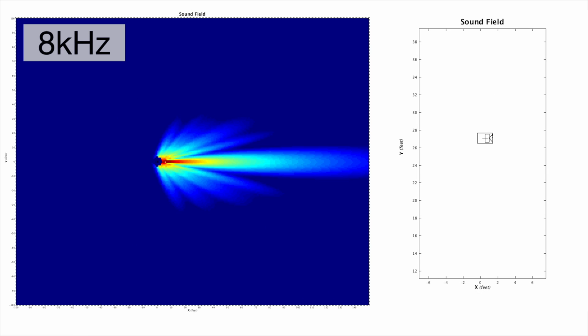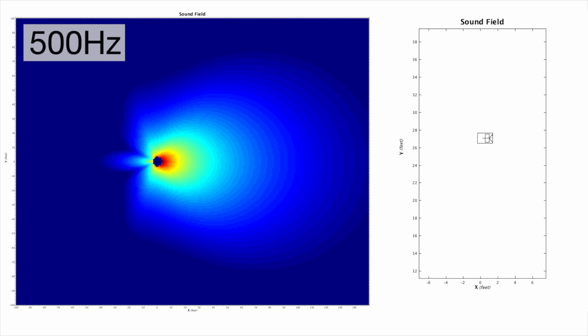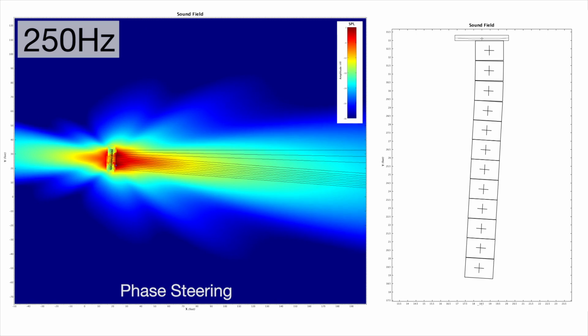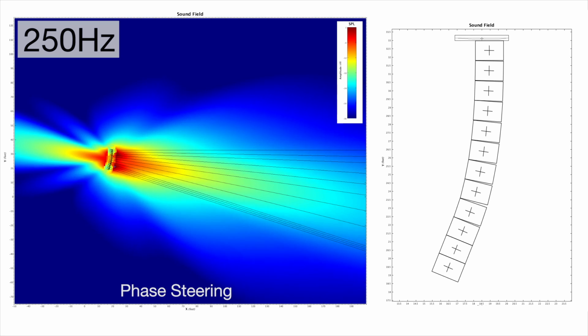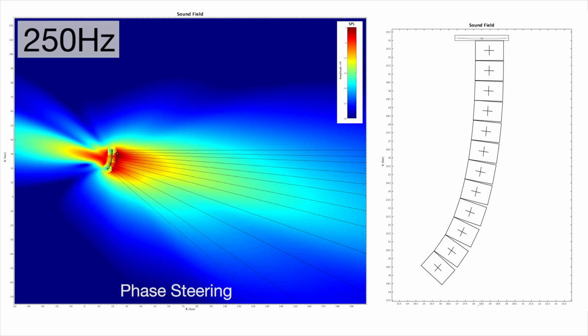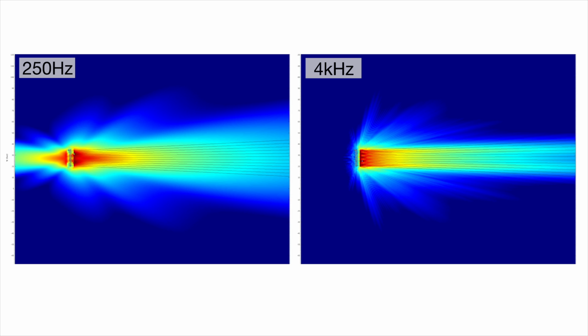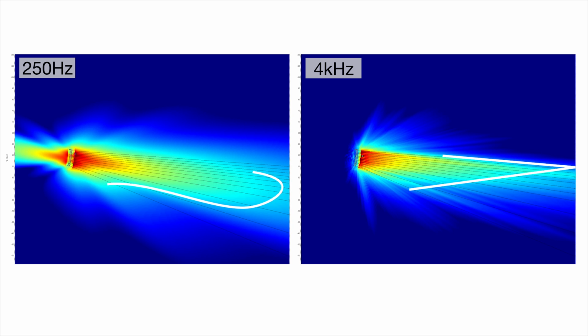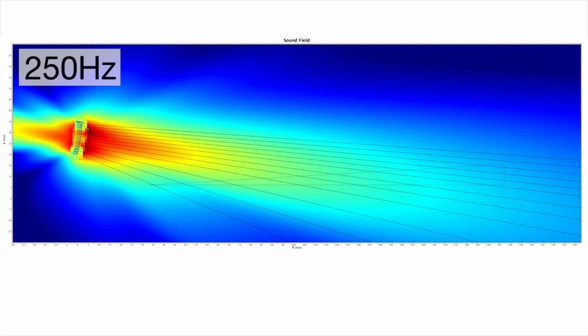Amplitude steering becomes progressively less effective as the wavelengths become longer in the lower half of the spectrum. Phase steering is the dominant force for this range and presents a significant challenge. In its standard form, the coverage shape in these ranges does not track the sculpted shape of the higher frequencies. A single beam emerges that is typically aimed too low and often too narrow and variable in both cases over frequency. This leaves us with a complex yet limited challenge: reshape the lower range without reshaping or compromising the upper range.